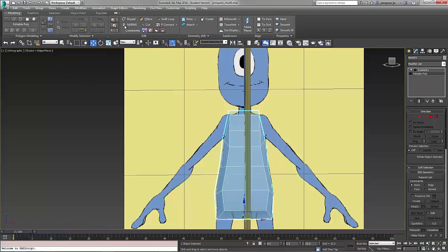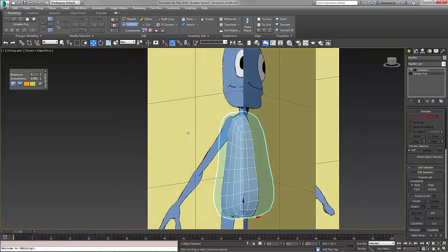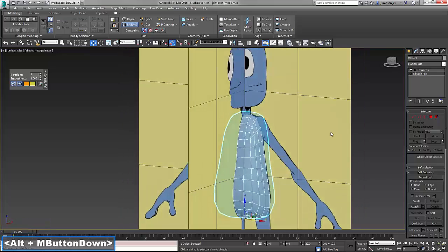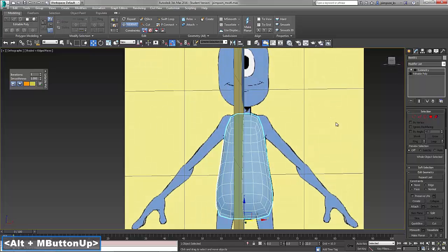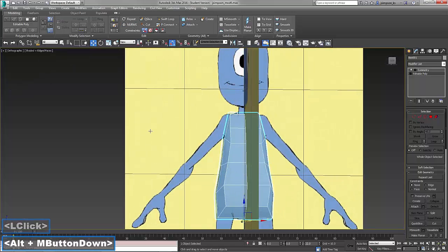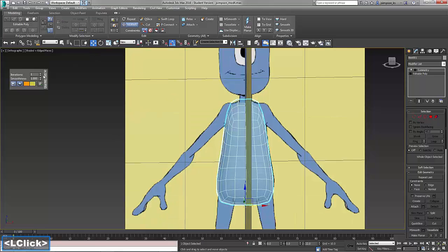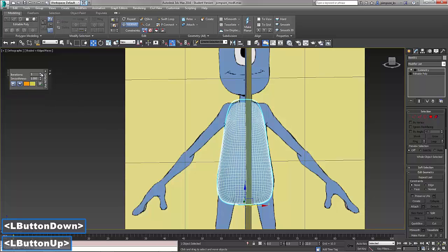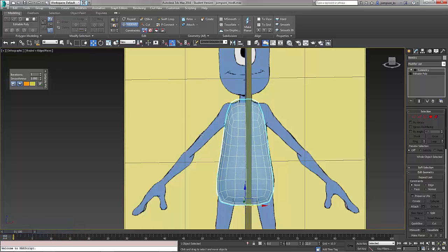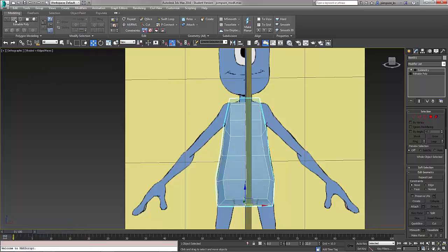In the Ribbon Modeling tab, Edit, select NURMS. This will smooth the model and give it a soft, organic look. Modeling with NURMS on can be difficult, so for now we are going to turn them off. But we will be adding NURMS again later. I just wanted to demonstrate them. A word of caution when using NURMS: keep the iterations to no more than 2 or 3 at the most, as this will increase your geometry exponentially and will slow down or crash your system quite rapidly.